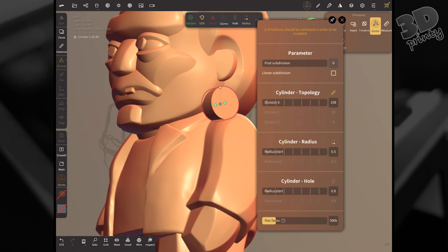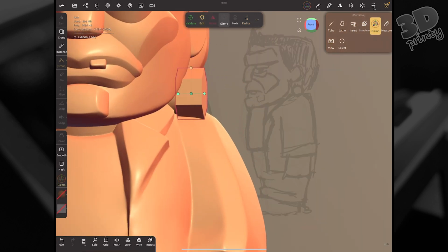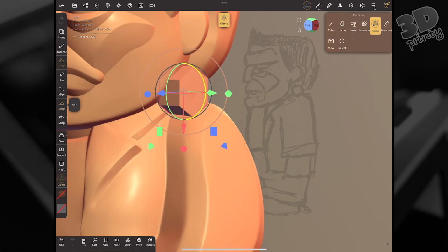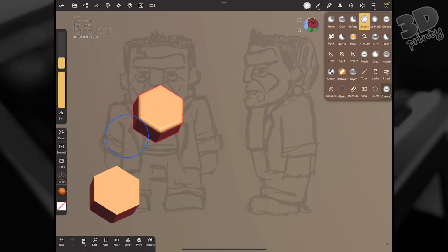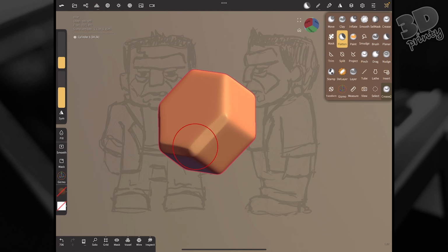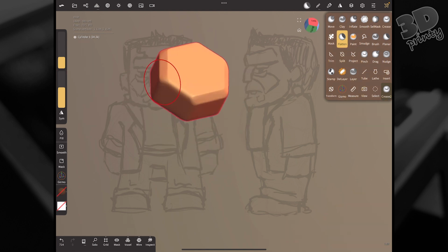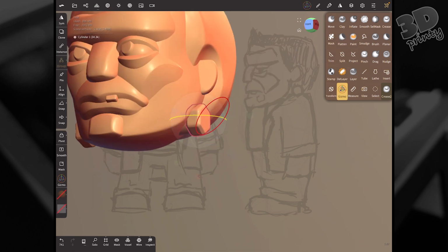This Frankenstein model doesn't have much of a neck, but I wanted to add the classic bolts anyway. So I added a cylinder set to a very low resolution, giving it only 6 sides. Then I rounded all the edges, and then squared them off using the flatten tool. This gave the bolt head a nice hand-forged look. Then it was just a matter of figuring exactly where these bolt heads would fit.